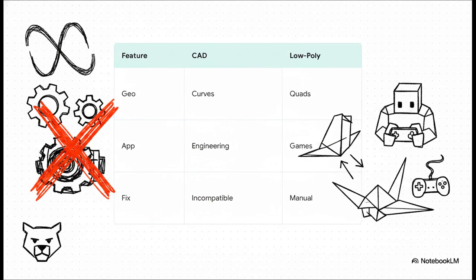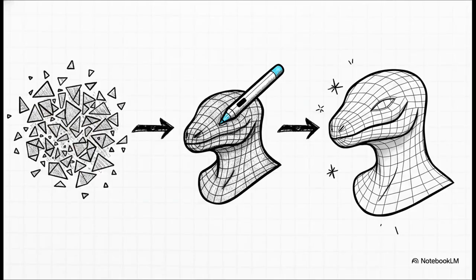They require manual rebuilding. Because automated triangulation produces totally broken geometry, flipped normals, and overlapping vertices, you have to use specialized tools. You need to be proficient in Blender's Retopo Flow, Maya's Quad Draw, or ZBrush's ZRemesher to manually draw clean polygonal strips over the CAD reference. Then you execute a high-precision, high-to-low normal map projection to bake those infinite mathematical details right onto your low-poly mesh.